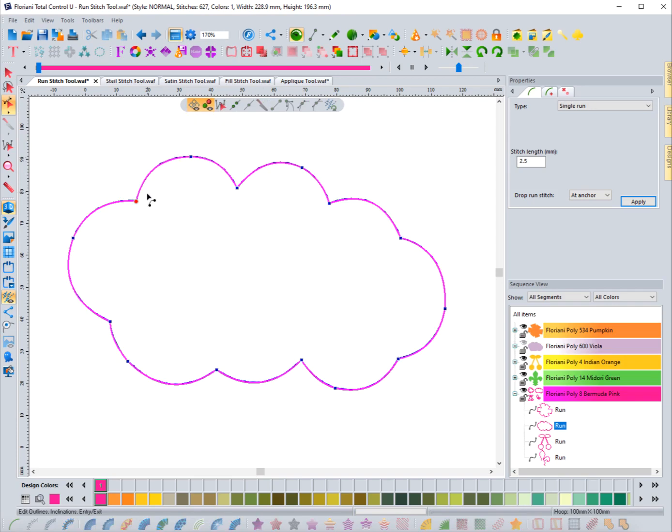That's what allows me to really come in and edit this, and not only edit the lines, but also the properties. You can click and drag, and you can change the type of point that it is. This right here is showing me it's a cusp. I could change it to a smooth, and by smooth, what it does is allow me to have a more curved shape right there.